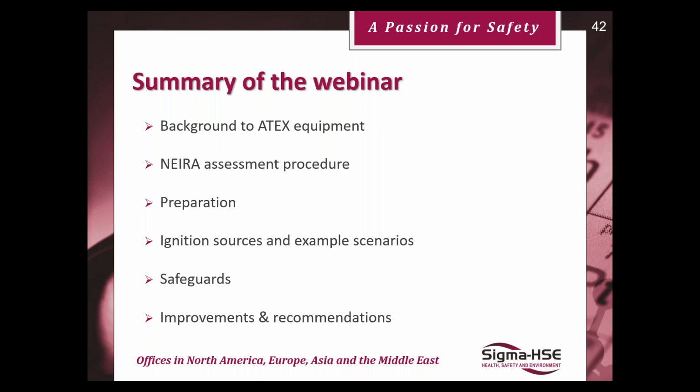So what comes out from a non-electrical equipment ignition risk assessment, a NIRA, which is the technique. And that can be applied, as I mentioned, to a range of equipment, typically mechanical equipment, but it can apply to low risk equipment like valves, even just surfaces, even just static pieces of equipment like a storage vessel.